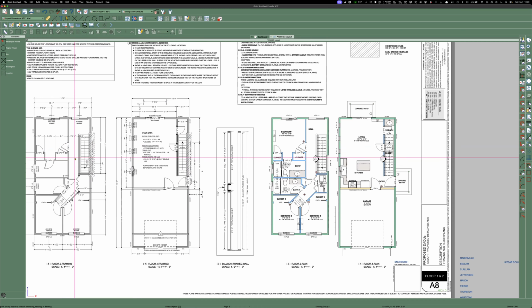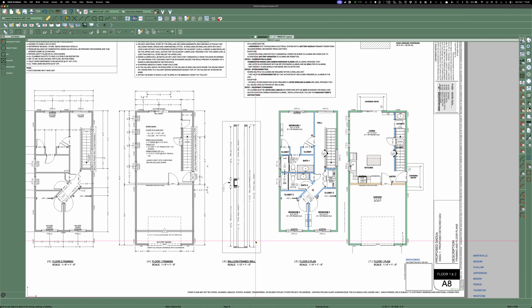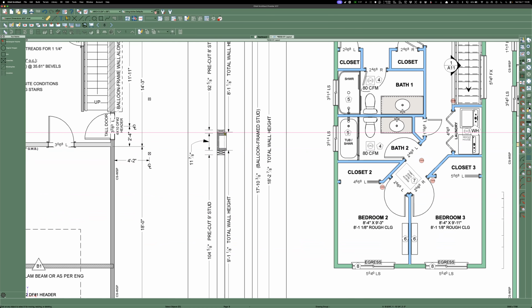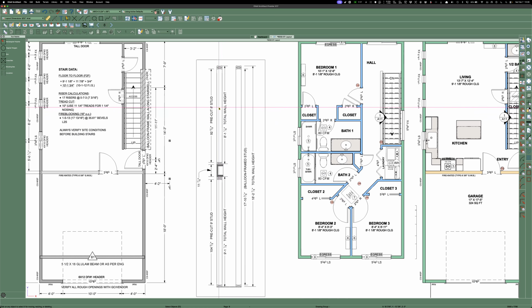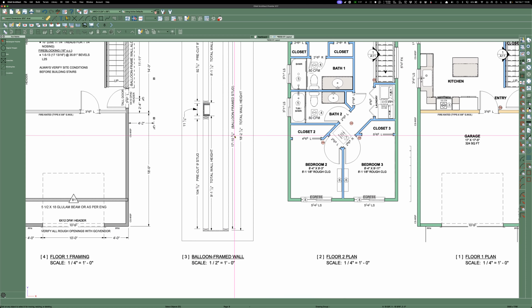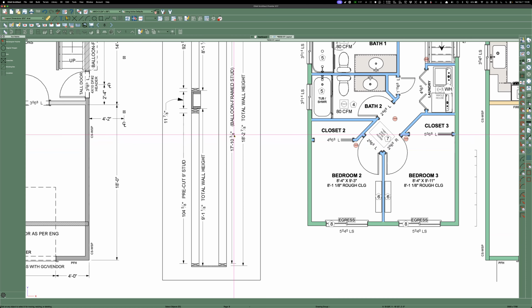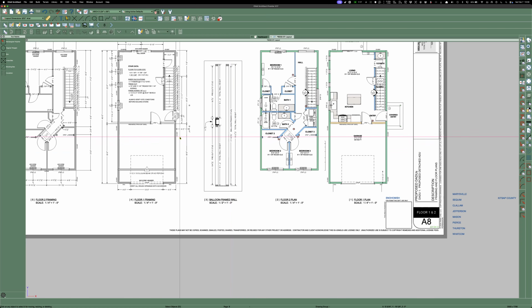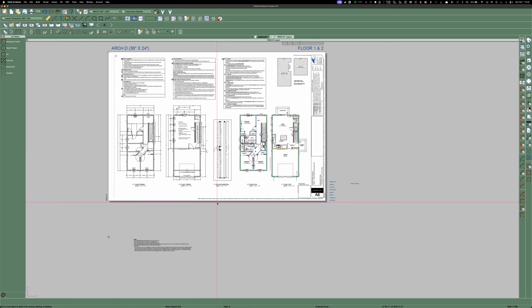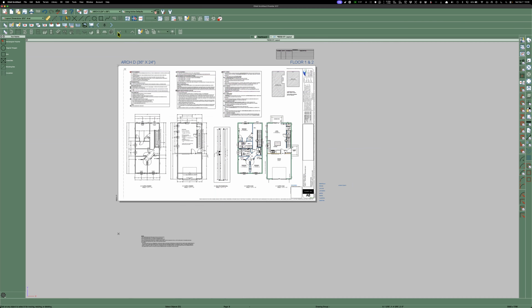So I boxed it in and told the framers, balloon frame this stuff. So I thought I'd help them out. Here's your pre-cut 104 5/8 9-foot stud. Here's your 11 7/8 I-joist, your 3/4 subfloor, and then here's your 92 5/8 second floor pre-cuts. And what that gives you is, if you do all the math, you can cut your balloon studs this tall. And a good framer is going to think that the designer doesn't know what he's doing, and he's going to double check with his own methods. So don't just trust me, but trust me, bro.